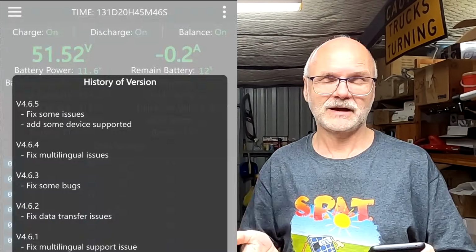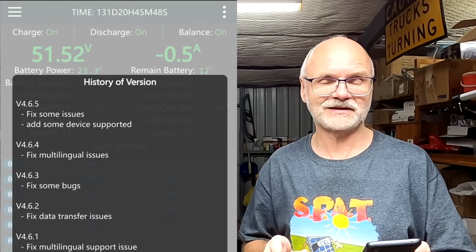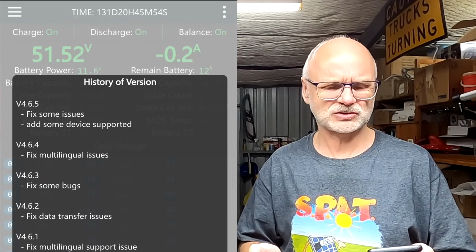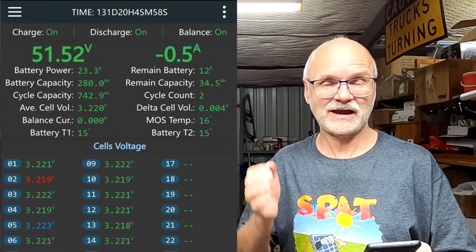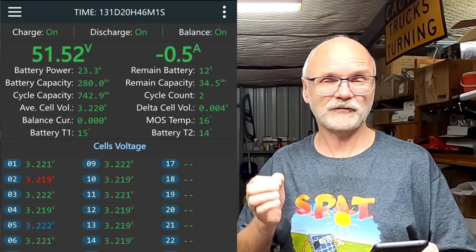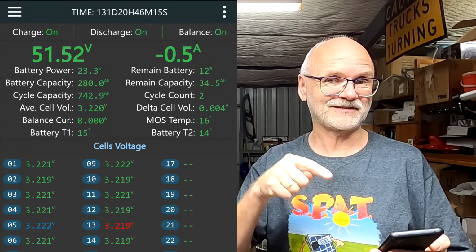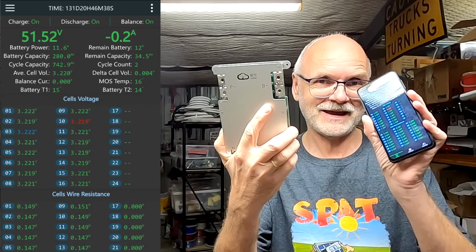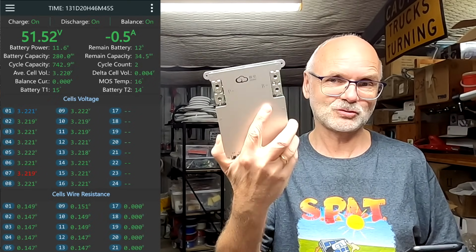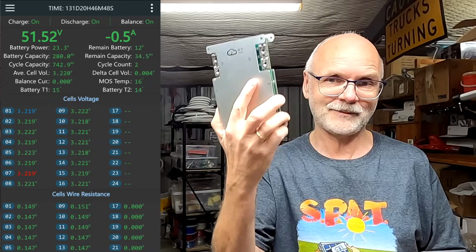Okay, history of version. I'm currently running version 4.6.5. Not even sure if this is the actual version here because they're changing and the app doesn't update automatically. So you have to go to the website and look for a new version there. I link this website down under the video and also on my website in the BMS section, so you can always find it there. As you may remember, when we tested the 4S version of the JK-BMS, I was not able to connect because my app was not up to date. So always make sure if you get new hardware from JK to update the app as well. It doesn't do it automatically.